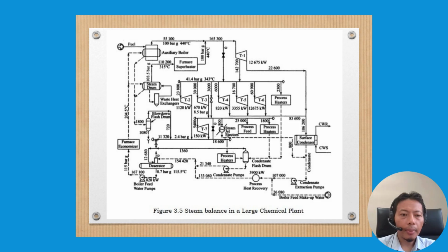This is an example of a complete piping and instrumentation diagram. As we can see here, different sections and equipment are linked with certain types of connections, and all of the elements in a P&ID are labeled according to standard symbols to show their locations, their functionalities, and their roles in a particular chemical process.